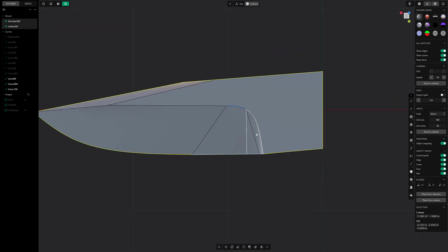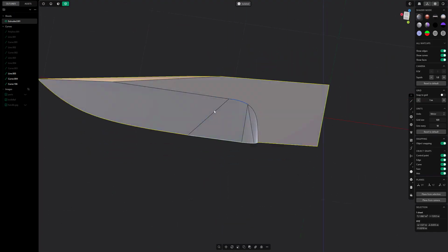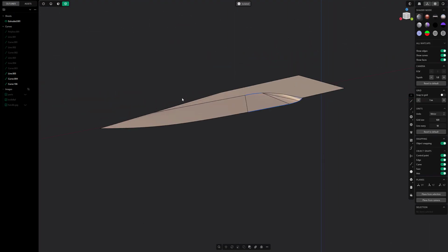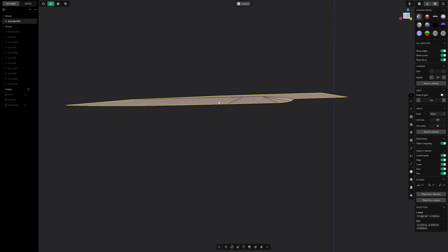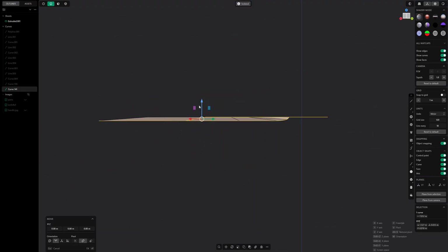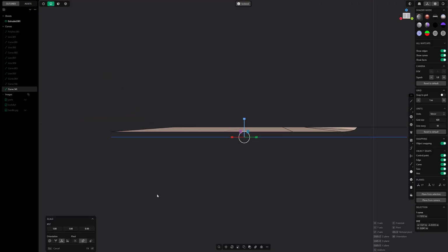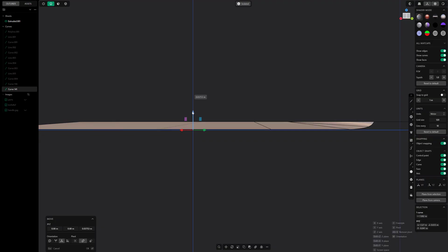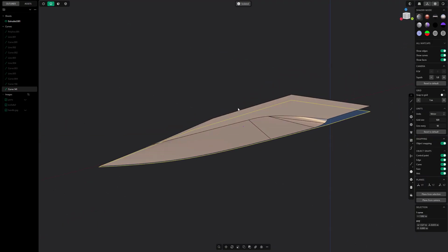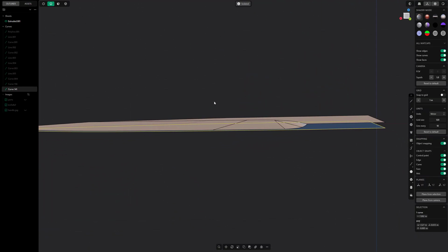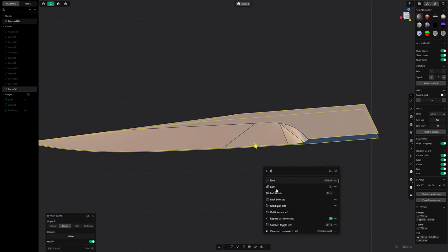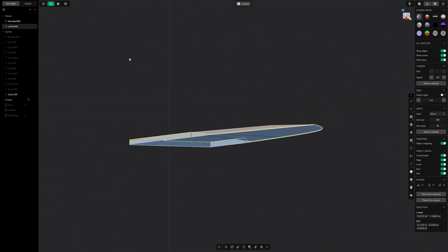So I'm just, again, establishing the shapes. I can always go in and take one of those edges, pipe it to get some separation, and then re-loft in between if I feel like my transitions aren't good. I take the whole border edge and I duplicate it, and then I just Z-fight it down, or smash it so it's flat. And this is going to give us the thickness of the blade.